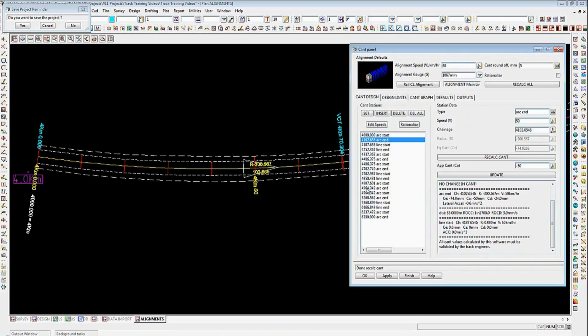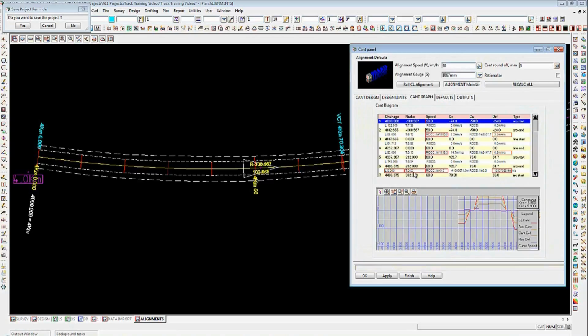And what we're going to do there is pick on the first of the two chainages that are identical. I'm going to come across to the right hand side over here and change that from 64 down to 54. I'll update that one. Then I'll come down to the next line down here, update that from 64 to a 74 and update that. That basically has told me that I've now got a 20 meter distance through those portions in there.